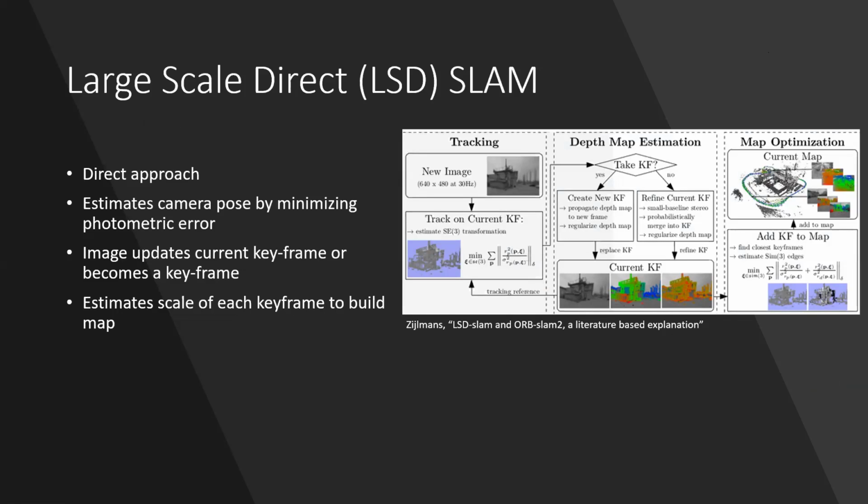So it's estimating the camera pose by minimizing photometric error between the different frames and the different images that come in. And so you kind of have to use a principle similar to structure from motion, but basically in each frame, you have to track the images you're looking at across them to then build up an idea of where you might be in the frame, because you don't have great data on depth, like we were talking about earlier.